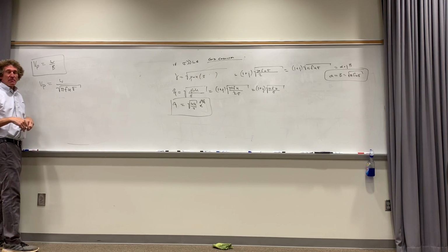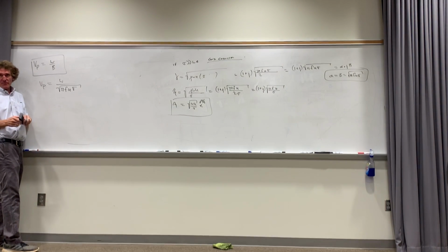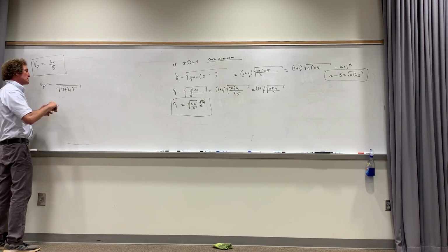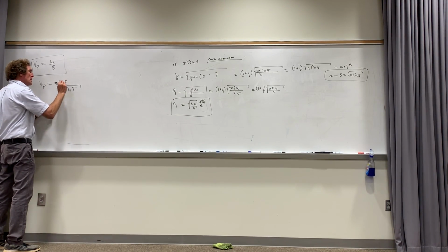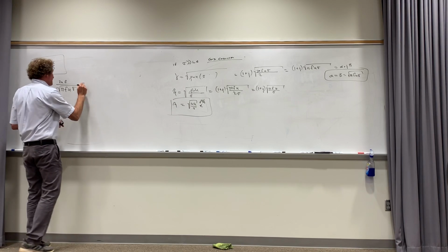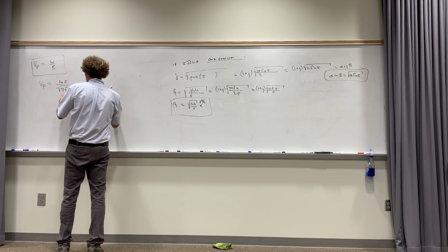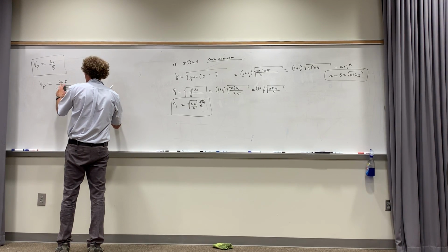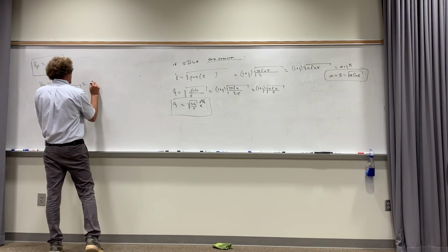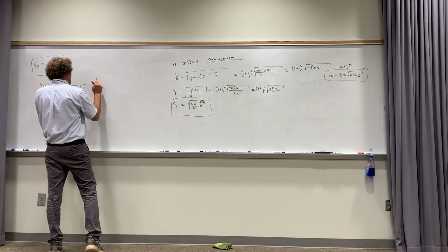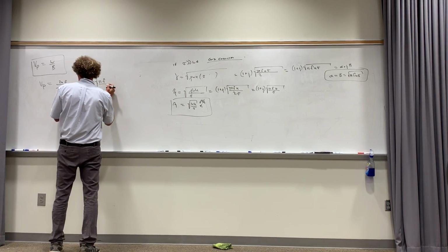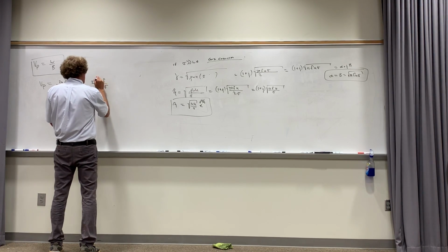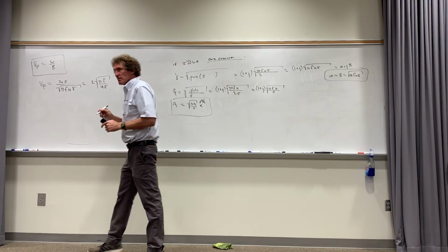Now, do y'all see here omega can be replaced by 2 pi f? Y'all give me that? With me? Sure. So now that's 2 pi f. Now, look what happens. When I do this, I have pi f, I have pi f. I mean pi f square root pi f. So that means I'm going to have 2 times square root up here of pi times f divided by what? Mu times sigma. Y'all agree?